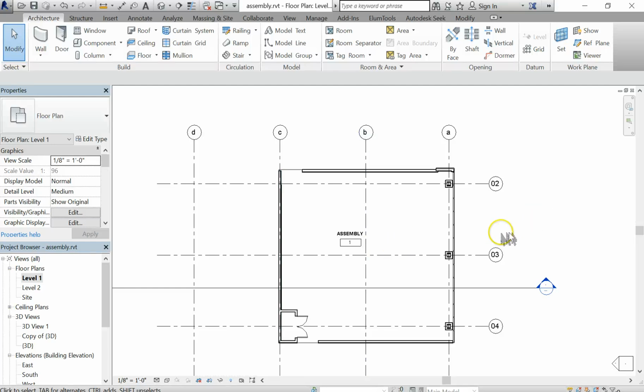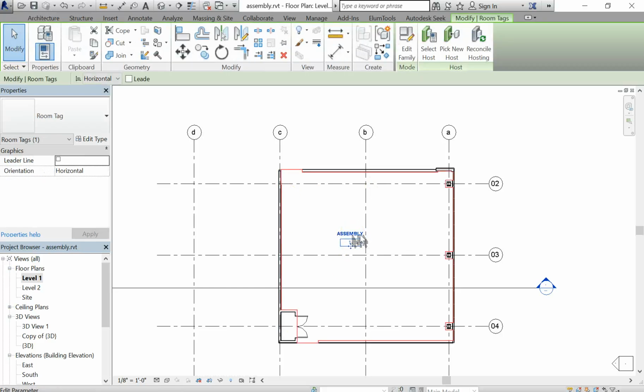In this video we're going to go over how to get from Revit into Ecotect and how to run an acoustical analysis on a simple room. So the first thing you have to have set up is your simple Revit model. You have a room placed in there that does touch all of the surfaces you want to analyze.